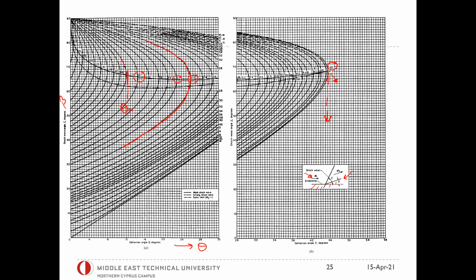So this is 1.5. If you're flying at Mach 1.5 and somehow you have deflected some surface higher than this angle, so if theta is greater than theta max, there is no solution to that equation. So you will not stay on this curve. If you remember, we said that that creates what we call a detached shock wave.